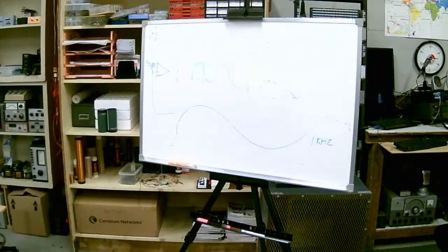And if you have an infinitely sharp pulse, like a radar pulse, well, it's not infinite, but a super sharp pulse, like this duty cycle here, you end up with every possible frequency from DC to daylight. Not just the harmonics, but every frequency in existence. An infinitely thin pulse, the short pulse, gives the entire radio spectrum. Does anything do that? Well, radar comes close to it. Radar is very wide.